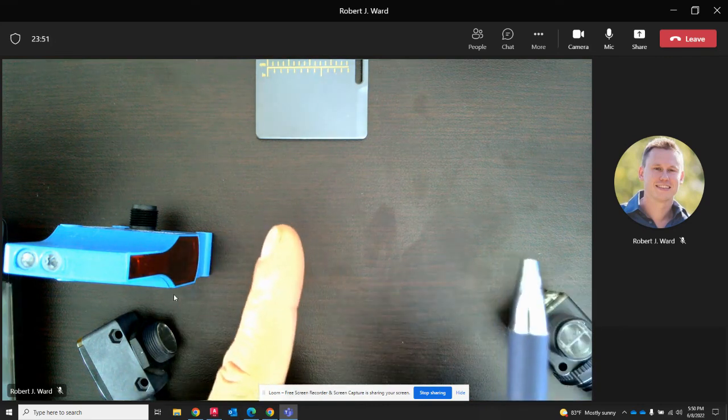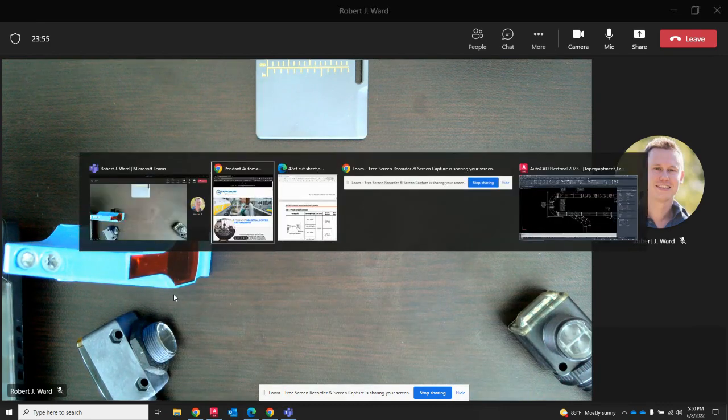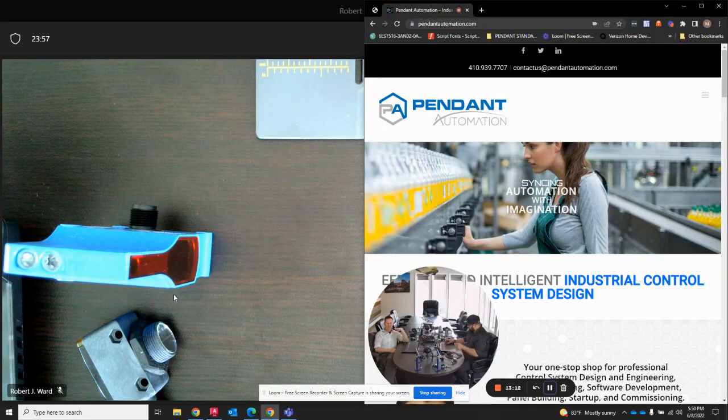Right. And that's a consideration. I know we don't do too much machine control, but if you did machine control, you absolutely have to calculate that into your engineering, because you could put a photo eye there that you're looking to sense product that's an inch away, and it's outside of that window, and you'll never sense it.